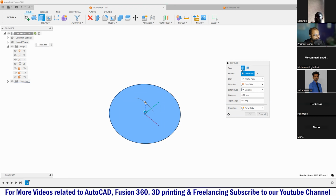Right now I want to extrude, so definitely the extrude option is selected. Then the next thing is it is asking me to select the profile. By default, because in this sketch there was just a single profile, and when I say profile, it means the closed area, closed space. So in this sketch there was just a single profile, that was the circle. So it is already selected by default.